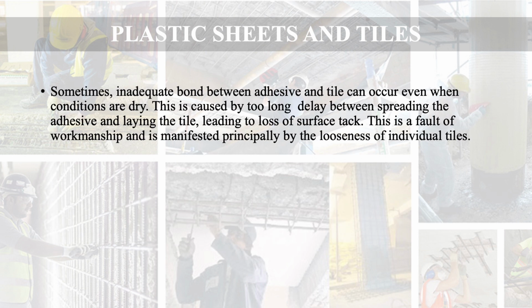Sometimes inadequate bond between adhesive and tile can occur even when conditions are dry. This is caused by too long delay between spreading the adhesive and laying the tile, leading to loss of surface time. This is a fault of workmanship and is manifested mainly by the looseness of individual tiles.